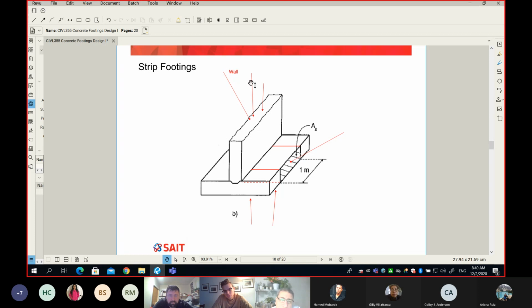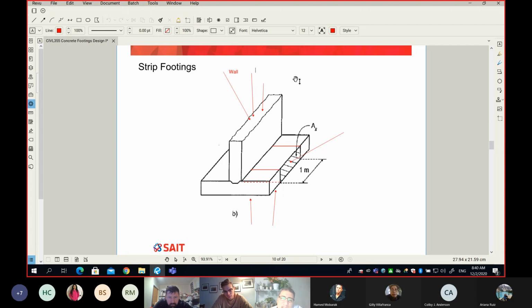I also need to remind you the load comes from the wall down to the footing. It is always estimated as, for example, PF. And what are the units? It will be kilonewton per meter, per linear meter of the wall. This is unlike the column. When we estimate the load on the column, what will be the units? Any help?